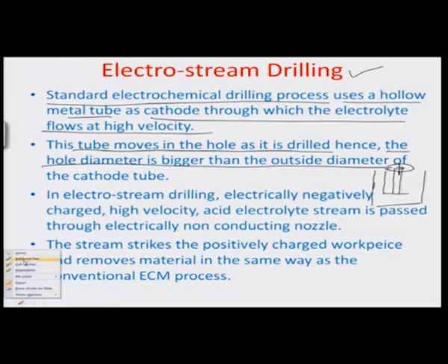So the typical overcut would be in this gap on both sides, because of the obvious reason that the dissolution keeps on happening wherever there is metal, and the surface of this electrode is also metal, just as the end of the electrode is, and therefore there is a dissolution creating this oversize.